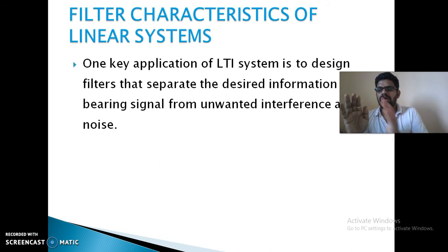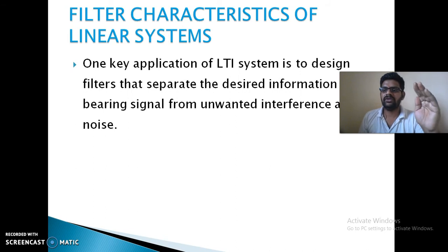It allows only some frequency components which are satisfied by that particular H of omega function. Only those components will be transferred as output. Otherwise, the remaining components are rejected. So it shows filter characteristics. It shows that an LTI system acts as a filter for some frequency components.